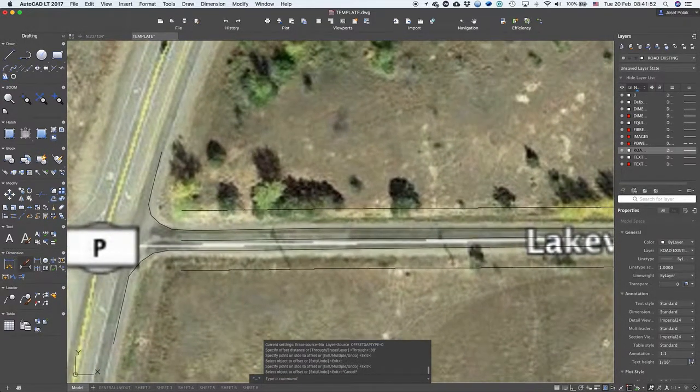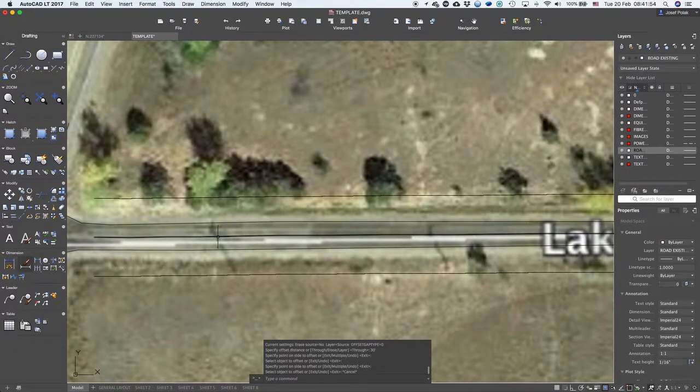Next step would be what I'm doing is you can see the road is bended here, and it's not an arc, it's just like a polyline. So I just create a spline, SP line, which makes it like rounded. So just double click, and you type S, and you have nice bend of the road, right?